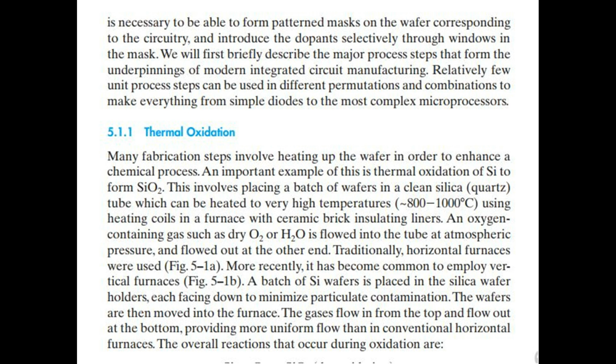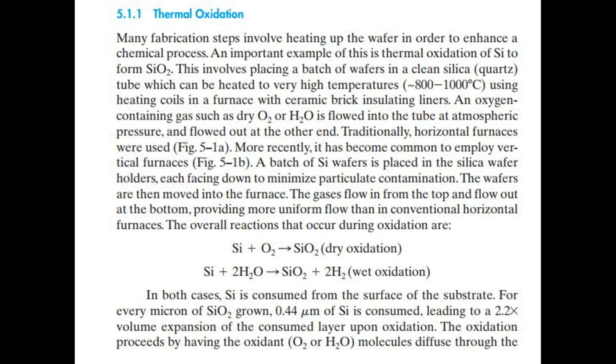More recently, it has become common to employ vertical furnaces, Fig 5.1b. A batch of silicon wafers is placed in the silica wafer holders, each facing down to minimize particulate contamination. The wafers are then moved into the furnace. The gases flow in from the top and flow out at the bottom, providing more uniform flow than in conventional horizontal furnaces. The overall reactions that occur during oxidation are Si + O2 → SiO2, dry oxidation,